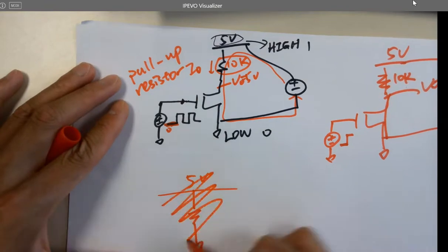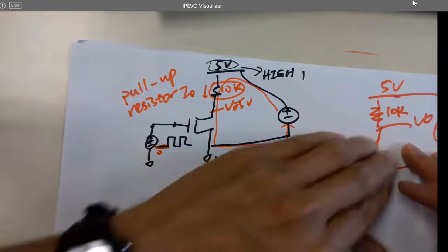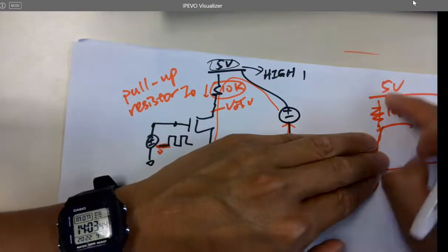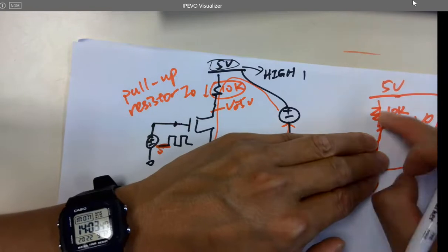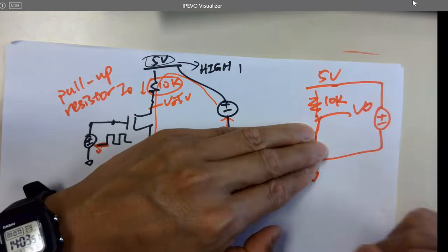Yeah, no, this is the best example. Whenever you don't have any current flowing into it, it pulls it up to 5, even though there's not that kind of action, it pulls it up. It's called a pull-up resistor, just remember it.